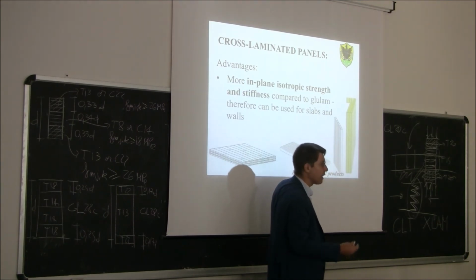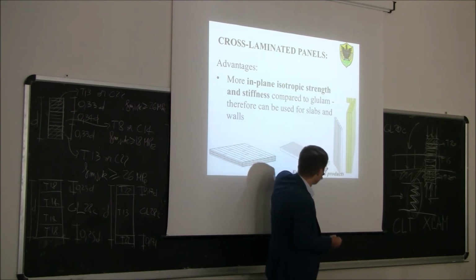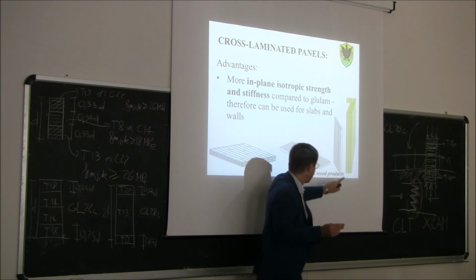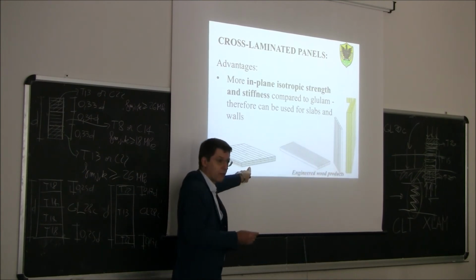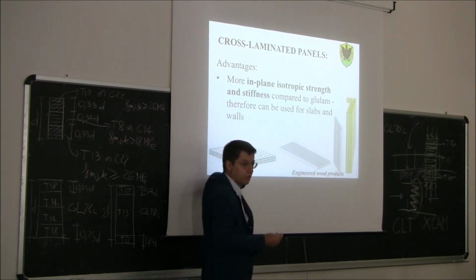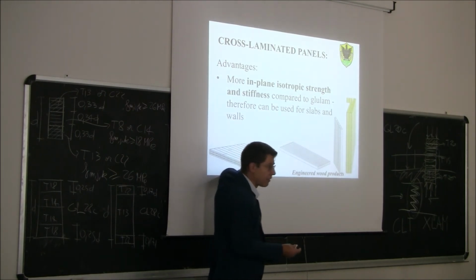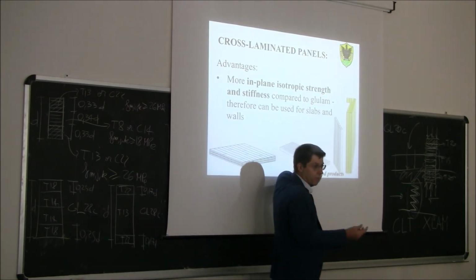Resistance parallel to the grain, yes, but for which cross-section? What is my resisting cross-section here? The entire cross-section. The entire cross-section, okay? Here it was not the entire cross-section. Here it was which fraction of the cross-section? 3/5. So here the realistic cross-section is 3/5. Here is 100%, everything. Okay?